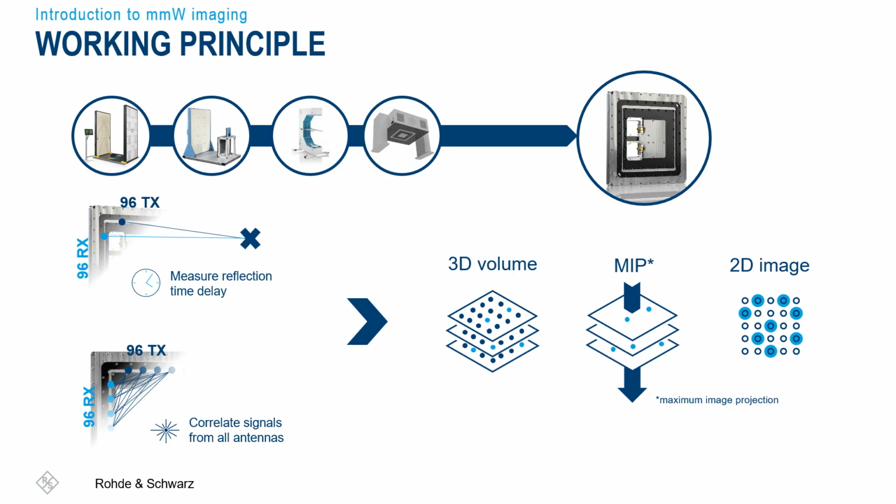So what we do to make these images easier to interpret is we can either look at each of the individual slices by stepping through them, or we can look at the so-called maximum intensity projection, or short, the MIP. So for this MIP, what we do in this configuration is we look top to bottom. We step through all the slices and look where is the voxel with the highest reflectivity for each of the Z vectors. That's how we create this 2-dimensional image.